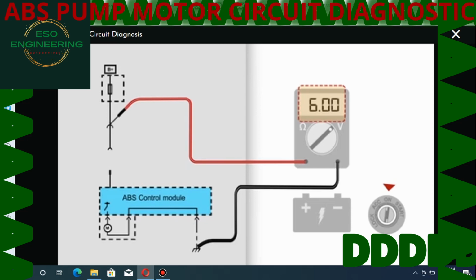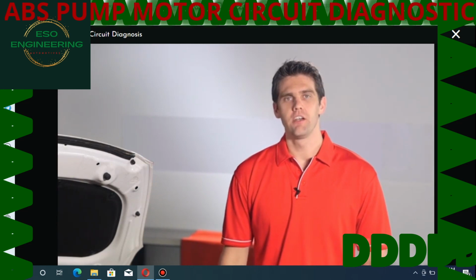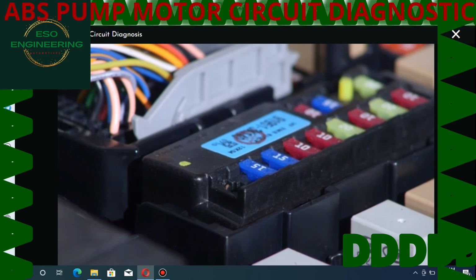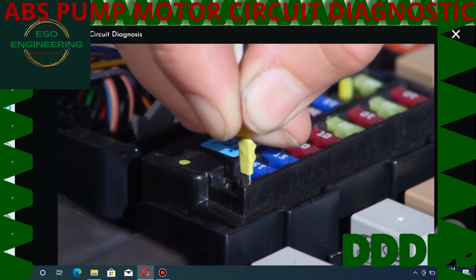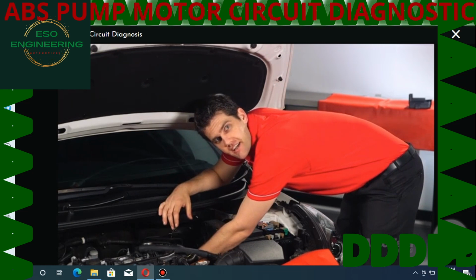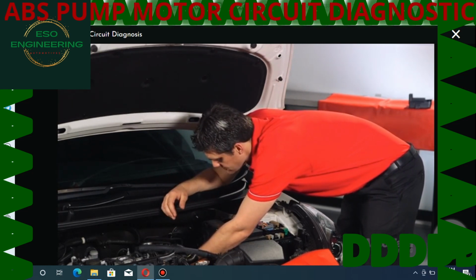If while testing, correct voltage is found after a connector, inspect the connector for corrosion and terminal tension. If the voltage at the fuse is low, the resistance is in the circuit to the fuse box. If voltage supply to the fuse is okay, confirm the fuse holder terminal tension is correct. If voltage supply tests okay at the ABS harness connector, check the module for corrosion and terminal tension.